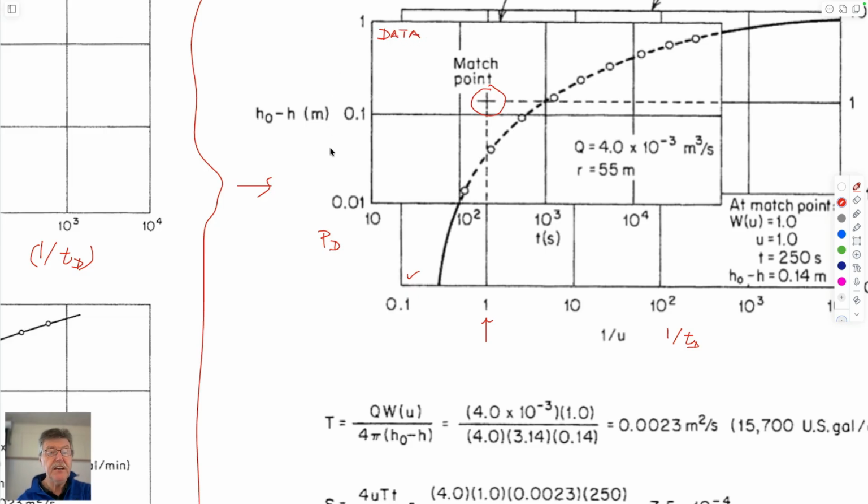So change in elevation in the wellbore versus time, you overprint them, and you put a pin through both plots where it's 1, 1 on the analytical plot, and whatever the magnitudes are for the values on the other plot. And those would be, I don't know, 0.2 meters and 2 times 10 to the 2 seconds.